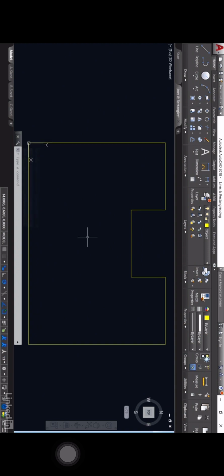So what I've got there now obviously is the ability now to draw lines in my model space in AutoCAD. It's that simple, and you notice there I've given you the direct distance entry method using polar tracking. Now, it may be that you need to use coordinates. It may be that you need to use snaps to draw lines as well.